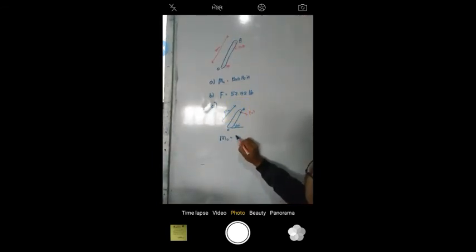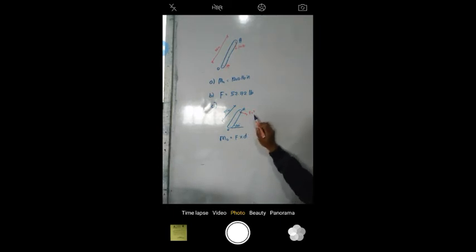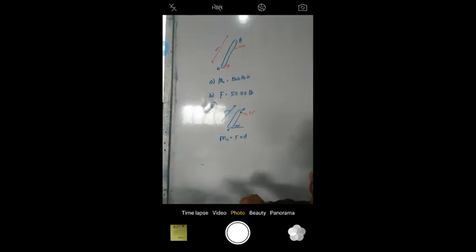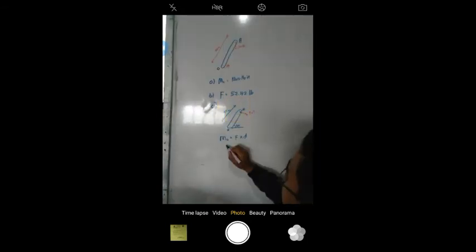Moment is equal to force times distance. So to find the smallest value of force, the D we should use is the largest one. This is the largest value of D, which is perpendicular to this 24 inches. Okay? You can see that.